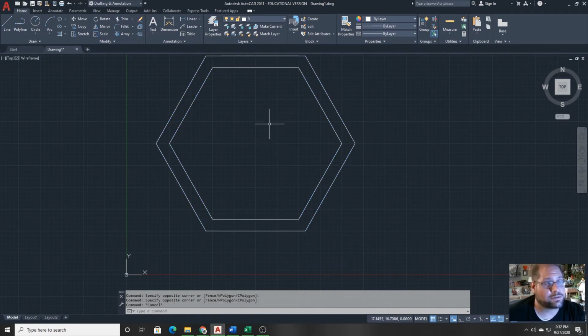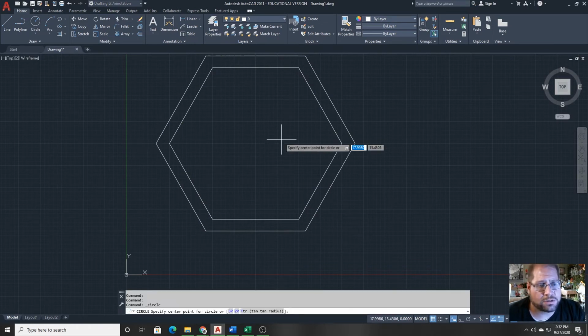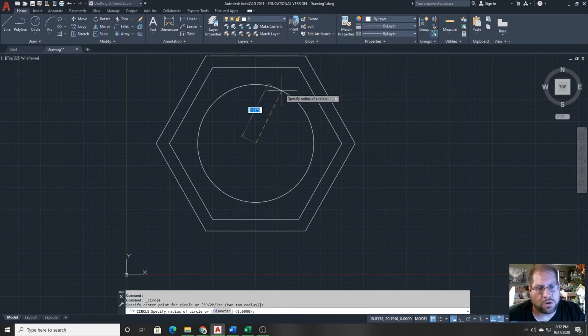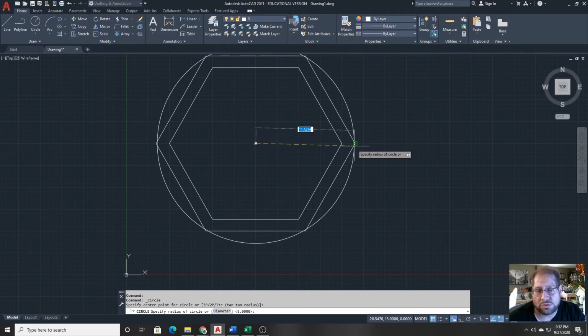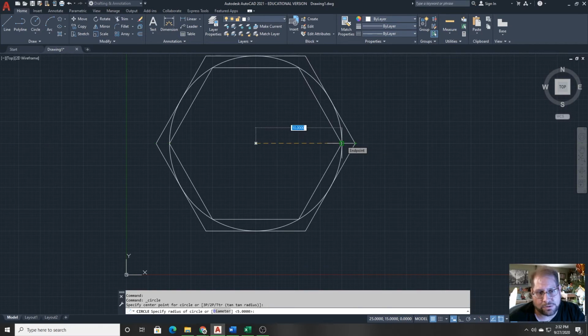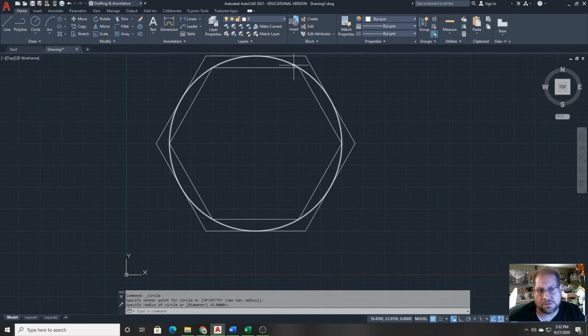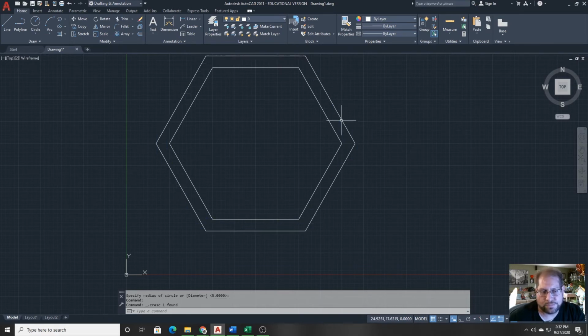And if you did ever want to see the circle, you could just draw it in. I'm just going to click the circle command right there and draw. You could see if I snap to this vertex, it would be the outer one circumscribed, but that wasn't the case. I'm sorry, the outer one that was circumscribed and the inner one that is inscribed. If I click that, you'll see these vertices are touching the circle. That's inscribed. On the other hand, the midpoints of the edges are tangent to the circle when it's circumscribed in this particular case. So you can see how that works.